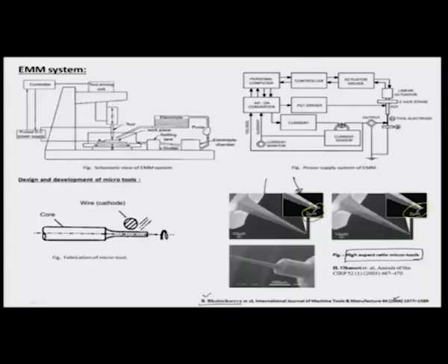like a glass pulling process, okay, which breaks the glass into almost the size of a 2 micron tip by virtue of shear at a certain higher temperature where the glass achieves flowability. Okay. But they have successfully done this 2 microns on metal using again the ECM process using a wire cathode, as can be seen here.